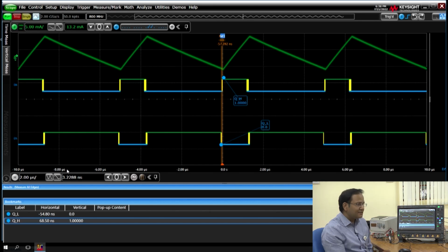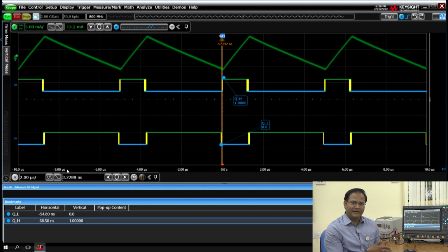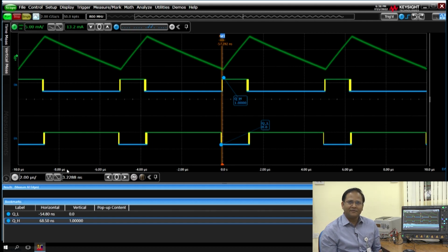As it can be seen, there are various functionalities that add to the extended capabilities of the oscilloscope. Digital oscilloscopes do not only have the analog capabilities, they also have the mixed channel capabilities. That means you can analyze the analog channels and the digital channels simultaneously, which is a very useful concept when it comes to debugging of such type of converters. Along with the voltage and the current signals, you can also analyze the gate pulses, what exactly we are doing in the system right now.